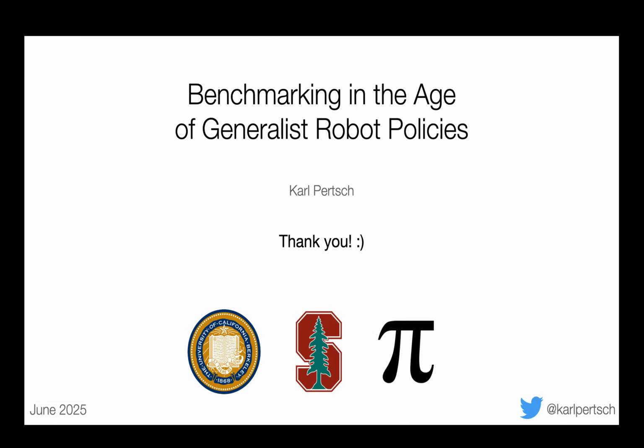One very common failure mode is that we typically only train them on demonstration data because that's the data that we collect. But then, in your evaluations, you really care about what happens if you're not perfectly demonstrating the right actions. In practice, if you look at some of these videos, when the robot tries to grasp an object and the policy misses, once it closes the gripper, the object teleports into it. Because in all of the data you trained on, whenever the gripper is closed, there's an object in it. And so these kinds of things make it hard to use video predictive models as evaluation tools right now.